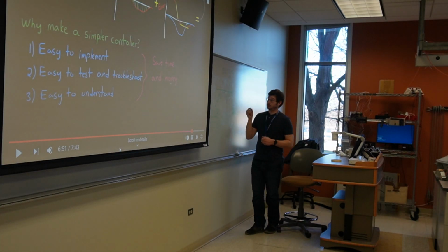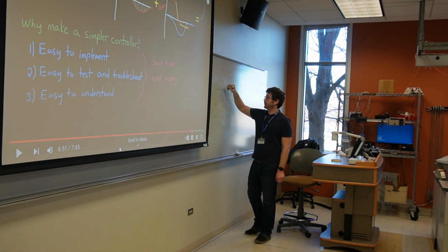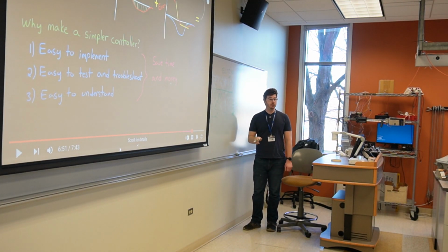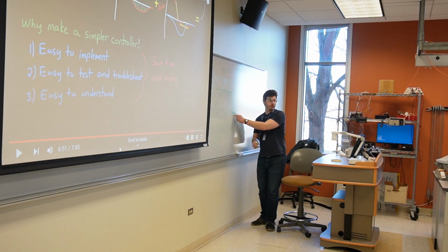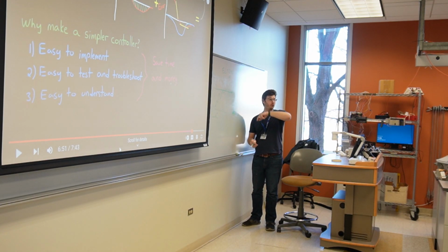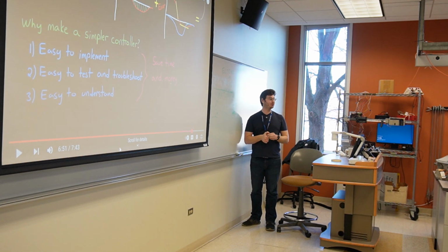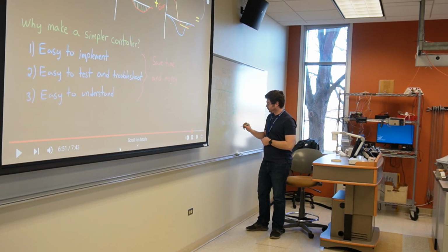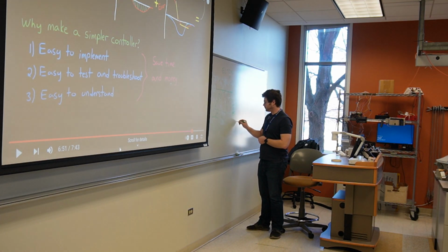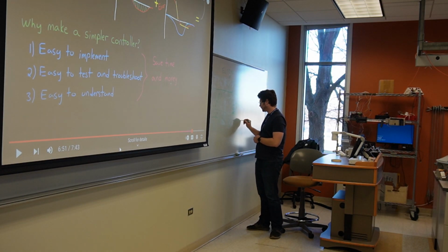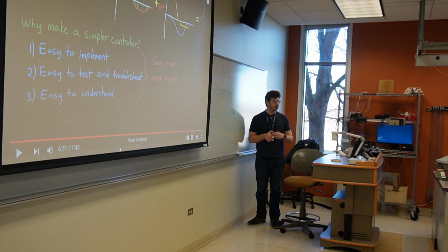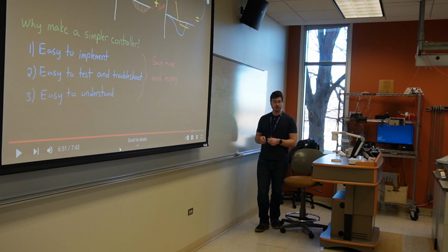And then what determines how well and how fast and how little overshoot and all that stuff is boiled down to three numbers. If you can figure out the correct three numbers to put here, your system will perform wonderfully. And if not, it'll perform terribly. Okay. The idea of figuring out what these numbers should be is called PID tuning. Oftentimes it's a manual process where you sit down and tweak these numbers and see how the system responds and tweak them again and see if you get a better response.